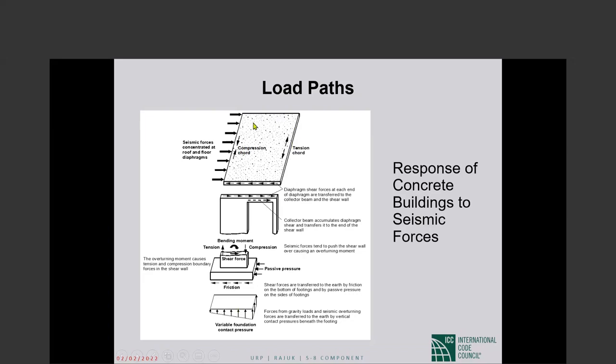Okay, so the load path in this case consists of the diaphragm, the vertical elements of the seismic force resisting system, the frames, shear walls, whatever they have, the foundation or the footing, and obviously then at the end, the ground underlying the foundation.